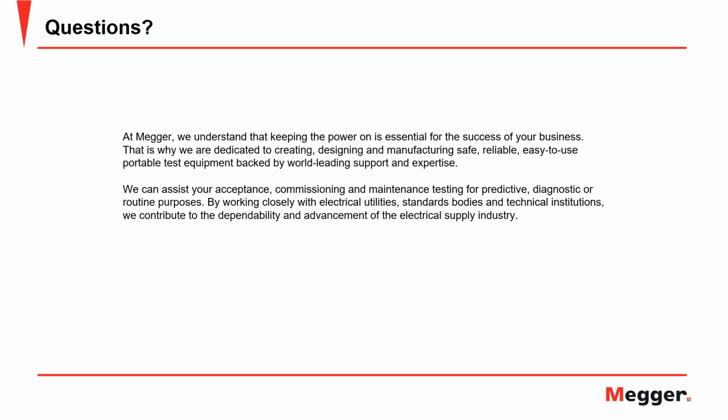Thank you, Dinesh. Sanket, what about PF measurement in the case of 3-winding transformers? So a 3-winding transformer, as I mentioned earlier, would introduce some additional elements. For example, on a 2-winding transformer, you have C high to low. Now, if you consider a 3-winding transformer, let's say with 1 primary and 2 secondaries, you would have additional interwinding capacitance in the form of CHL1, which is high to low 1, and then you have C high to low 2. You would also have interwinding capacitance between the first secondary and the second secondary.